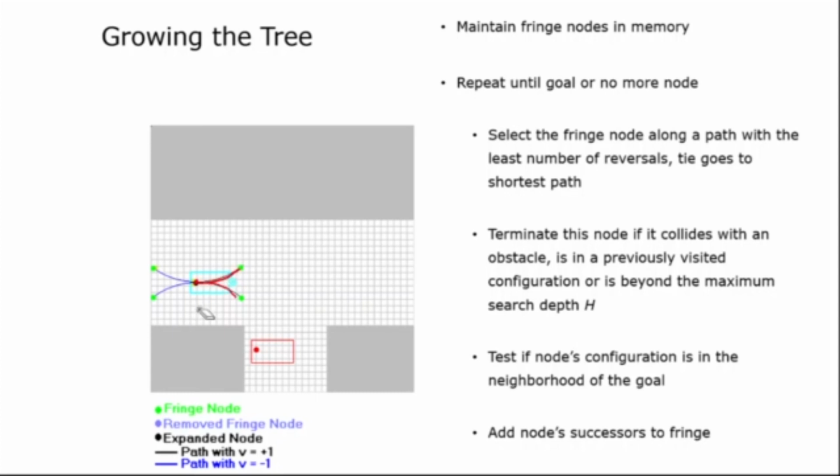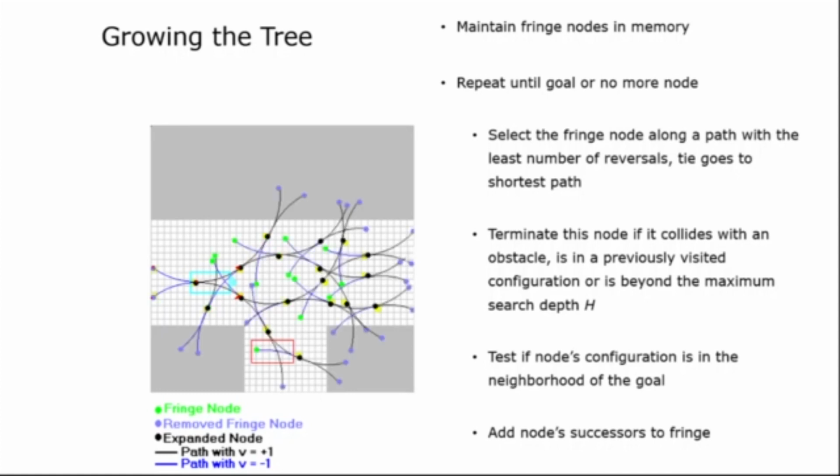So let's have a look at this again. Here, from here, I'm going to generate one node. It has generated one node here, one node here, one node here, and one node here. Then it catches this node and generates another few nodes. So it has generated another one here. It caught this one, generated another one, exactly the same way. It is catching one node at a time and generating nodes, and you see that it is covering the whole workspace. So it has covered all the workspace on all possible paths the car can take now.